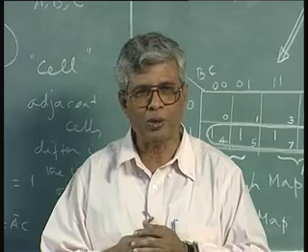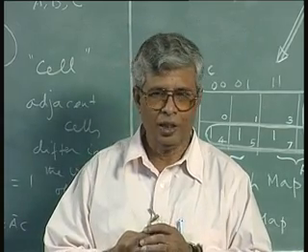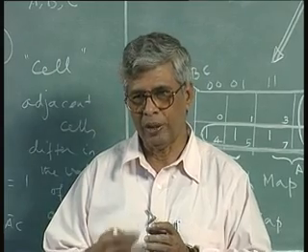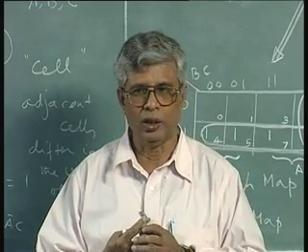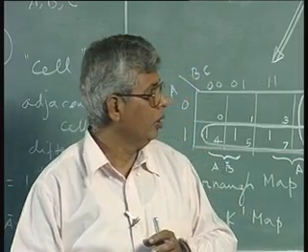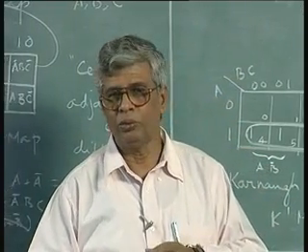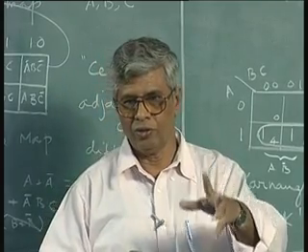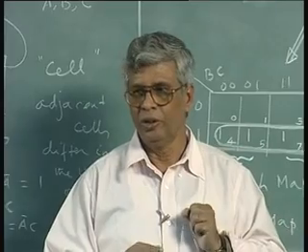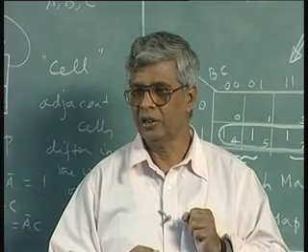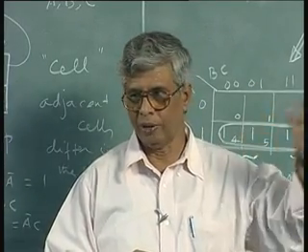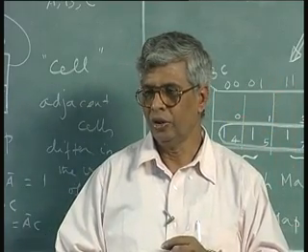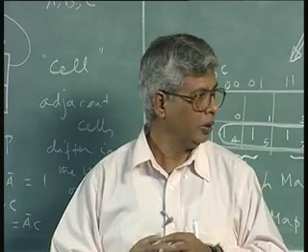There lies the difference between the Karnaugh map method and Boolean algebra, but Boolean algebra is what we have used finally. A plus A bar is 1 is Boolean algebra. It is not as if it is some new theory. It is a technique, a procedure maybe different, but not the theory. And now you can extend this to 4 variables. 4 variables will have 16 cells, 2 variables vertically, 2 variables horizontally, and you can do it like that.